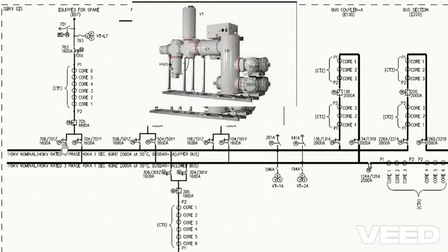Then there are the disconnectors Q1 and Q2. Before closing the breaker, you have to be sure which bus bar you want to connect with this bay. Accordingly, you have to close that disconnector. If you close this Q1, it will energize this bus. If you close this disconnector, it will energize this.